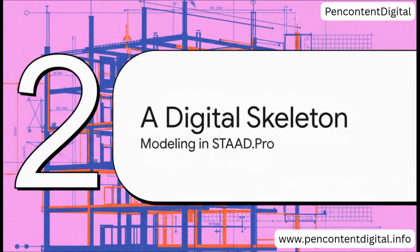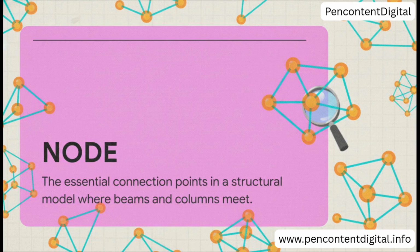So how do engineers get a building ready for this fight? Well, it all begins with building what you could call a digital twin, or a virtual skeleton. This is the very first step in the whole analysis, and believe me, it requires incredible precision. Everything starts with something called nodes. Just think of these as the joints in that skeleton, the exact points in 3D space where all the important parts connect. Getting these right is absolutely crucial because they literally define the entire shape and geometry of the structure.